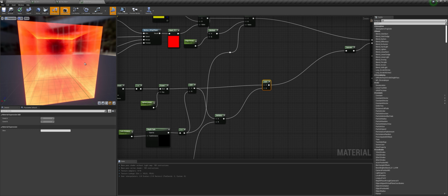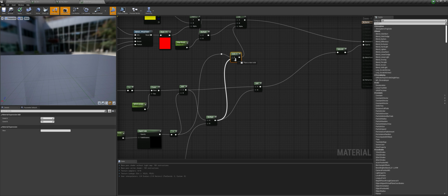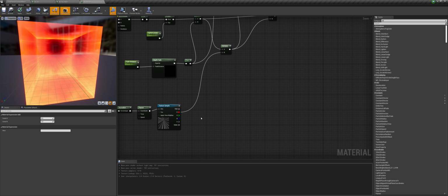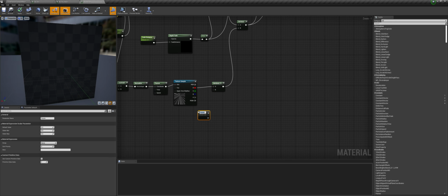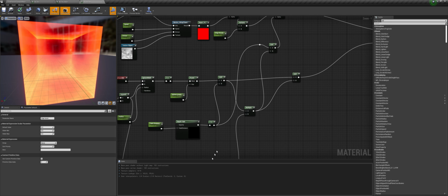So we want that lightning streak to have this boosted value. So in order to do that, we can get an add node and connect this here and connect this to the alpha, then connect this to the B key here. So you can see it here. Now we can get a boost for the lightning. So get a multiply and connect this here, and we will call this edge boost. I think we already have an edge boost.